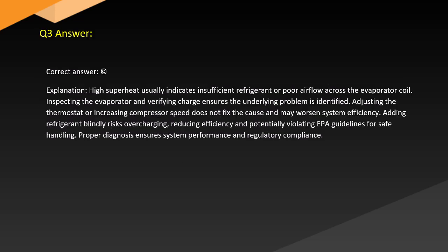Answer. Correct answer, C. Explanation. High superheat usually indicates insufficient refrigerant or poor airflow across the evaporator coil. Inspecting the evaporator and verifying charge ensures the underlying problem is identified.